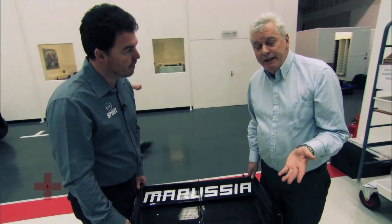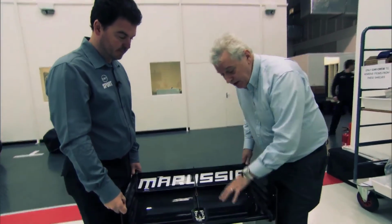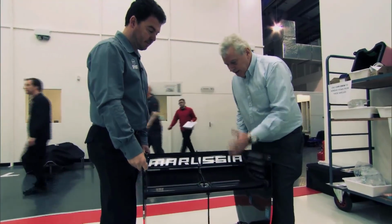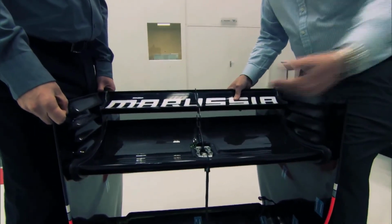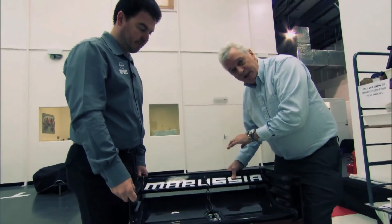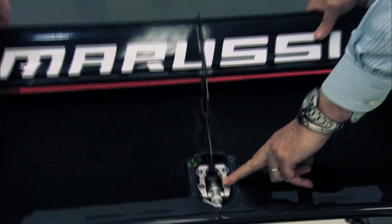Well, firstly, we call it the DRS. DRS stands for drag reduction system. Everyone knows that the wing is here to produce downforce, but in doing so it also produces drag. It slows the car on the straight. The DRS is a device that allows part of the wing, the rear flap, to move. By moving, we don't get so much upwash from the wing, we don't get so much downforce, but more importantly, we don't get so much drag. So we can pick up 10 to 15 kilometers an hour of top speed just by making this movement. It's moved by this hydraulic actuator which moves the flap thus.